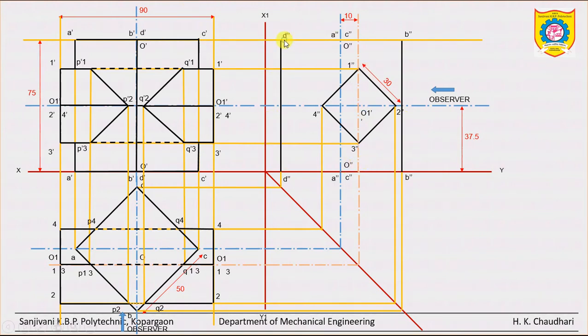Okay, and similarly this top faces. So this is the LHS view, and again edges A and C are intersected by the horizontal faces. So from the top, draw a vertical thick line up to the point where this edge intersects the horizontal face.